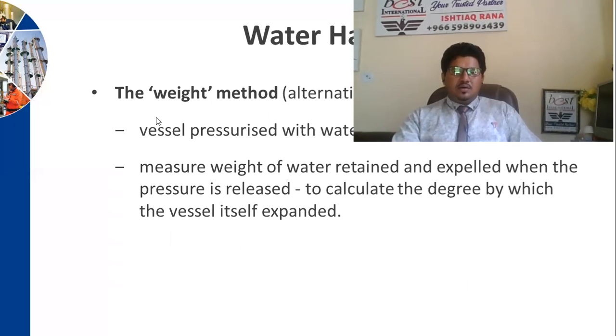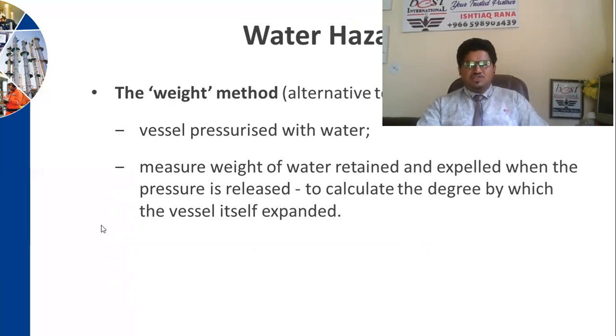We can use the weight method, an alternative to hydrostatic testing: the vessel is pressurized with water, then measure the weight of the water retained and expelled when the pressure is released, to calculate the degree to which the vessel itself has expanded.